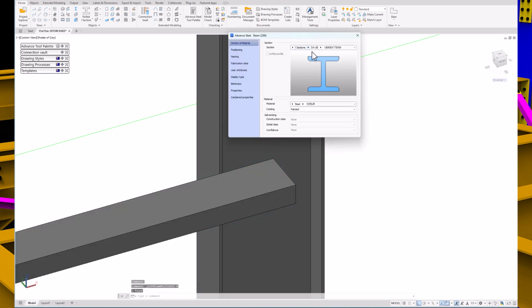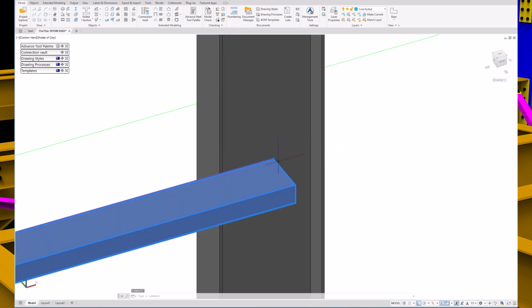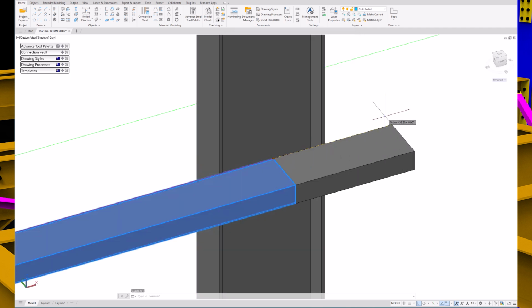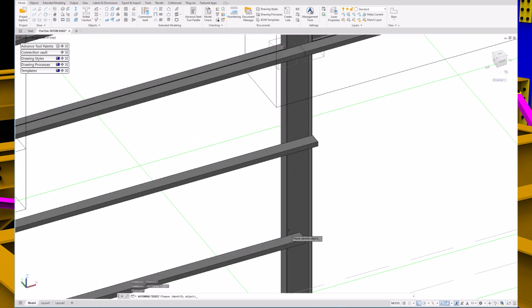This is a 4 or 6. That means that our pair line is exactly ending on the half of that column, so we need to extend by 2 or 3. Okay, so select the nodes, just type 2 or 3 on your keyboard. Go to the next pair line, select it, select the node, 2 or 3.